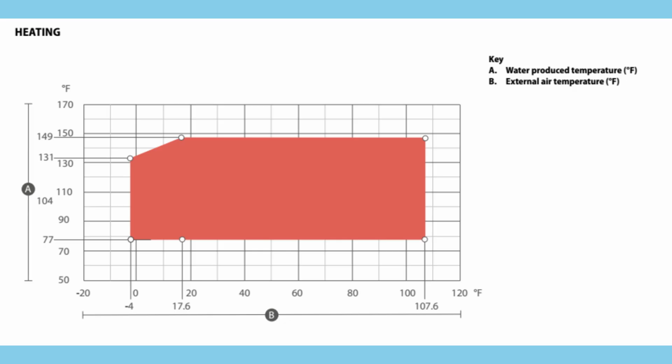For example, before switching to heating, the loop temperature must be raised above 75 degrees, but in summer, the loop temperature was around 45 F. We have to have some means, sometimes using boilers or supplemental heat for a few minutes, to raise the loop temperature above 75 F. That will allow the heat pump to run within its operating envelope, and it will not see any issue in the field. Otherwise, the heat pump will go on alarm, an out-of-envelope alarm or some pressure alarm.